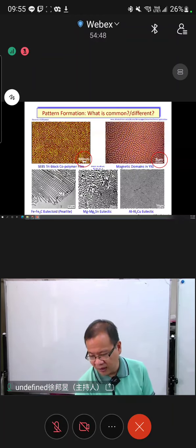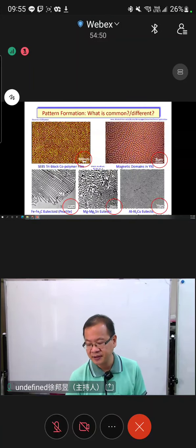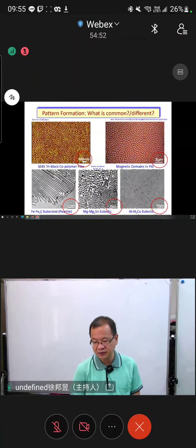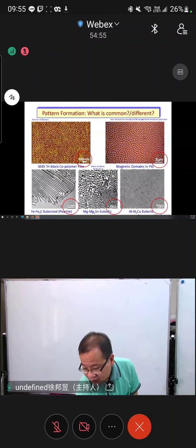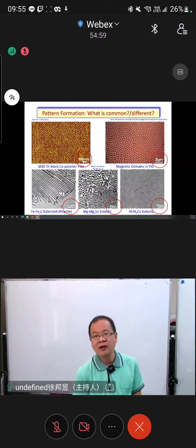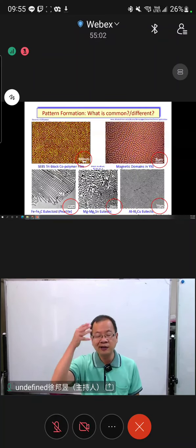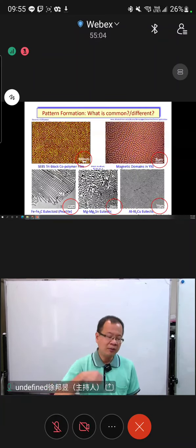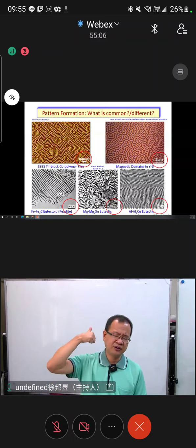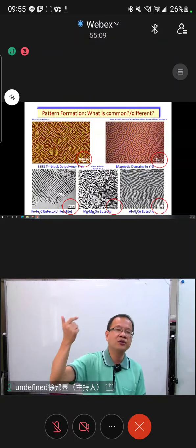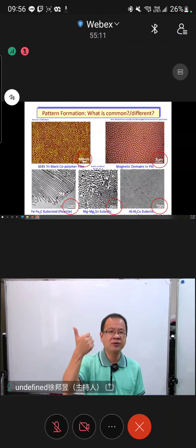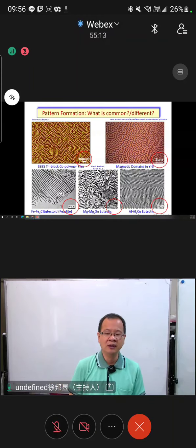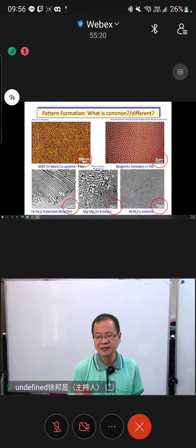And the bottom one is just another simple example. You can see the line structure repeats itself, also in very different dimension. All right. So one is 10 micron, the other two are 15 micron, but the structures are aligned, right? So it's all about the original crystal structure and what equation you grow with, and what equation of diffusion controls the growing. If they are the same, it's simply the problem of shorter or longer time, and that's it.